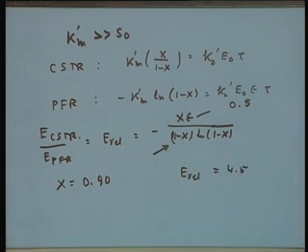That means the enzyme required for the same fractional conversion, 90%, in the case of a CSTR will be 4.5 times more than that required in the PFR. The same enzyme, the same reaction, same conversion level. The quantity of enzyme required in the CSTR will be much higher compared to PFR.